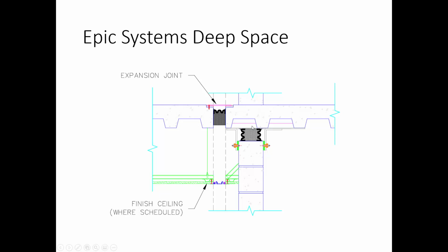If you have this building and you bring 25,000 people in there, the live load is going to drop the floors quite a bit. So we had to have all these sound isolation partitions that were flexible both vertically and horizontally. So we could keep the seal, and we could also stop the vibrations of the mechanical equipment from going side to side.